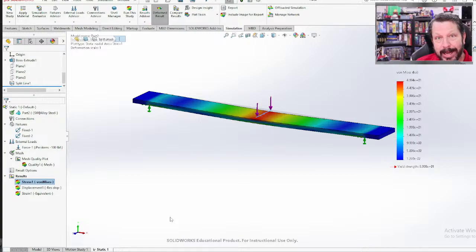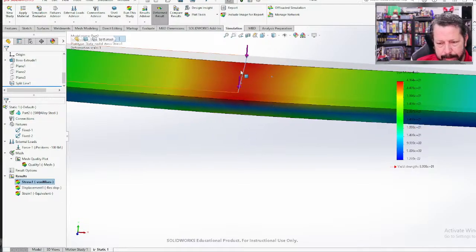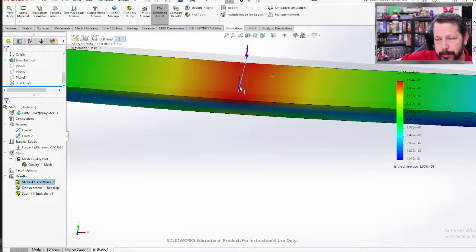We applied it to a line, right? And so probably if we had more detail, like more elements around this line, what we would see is that we're getting really high stresses right at that line, and they're compressive stresses. Literally the bar or our load pushing down on our member here, and the 67 number we had was probably a really high compressive stress right on this line.